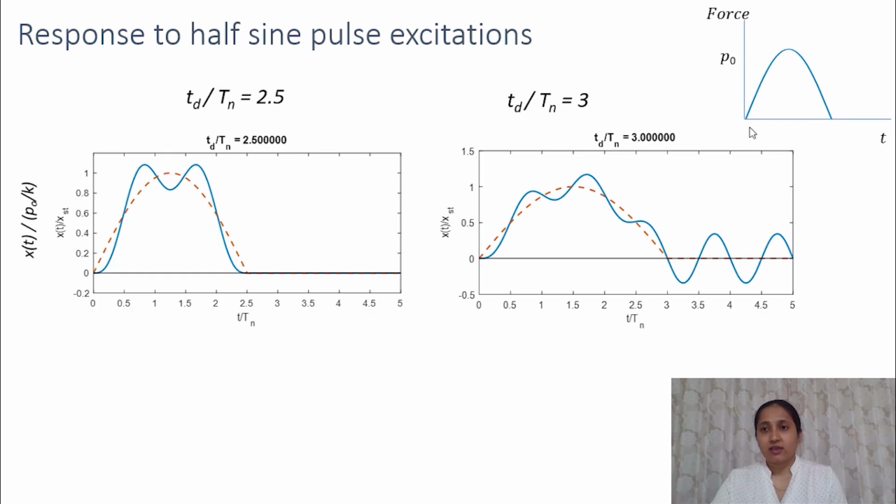That means as the duration increases, this pulse is getting flatter, and so the rate of loading is getting lower. That means the dynamic effects are reducing. The dynamic response is becoming closer to the static response. So as the duration of the pulse increases, this difference will come down.